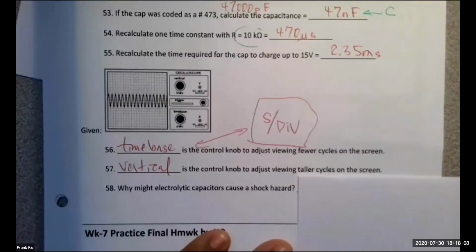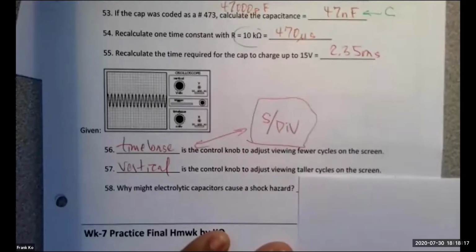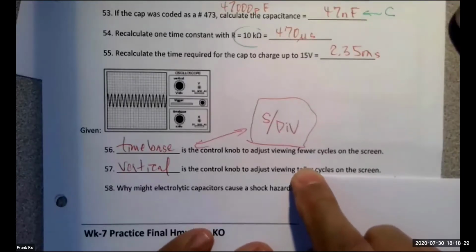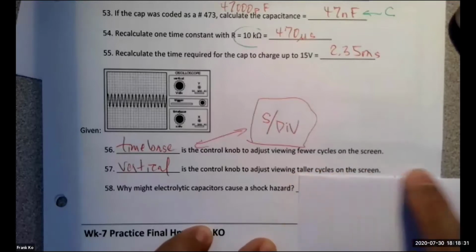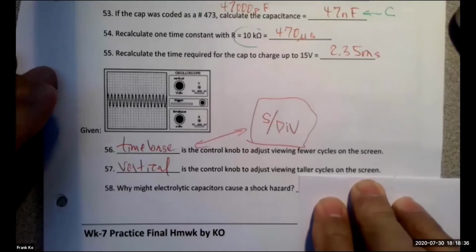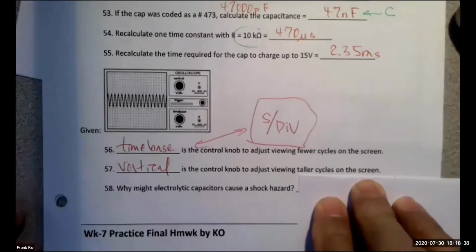When you turn off, first of all, you have the capacitor charged and it's able to hold a charge for a period of time. And so the shock hazard is, even though you remove the charging source, the voltage source that would charge the capacitor, because it can hold a charge for some time, it can still give you a shock, okay? It stores charge between the conductive plates and it can give you a shock. Any more questions on page 4?